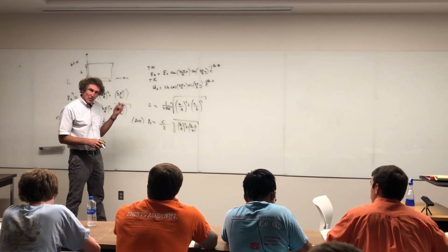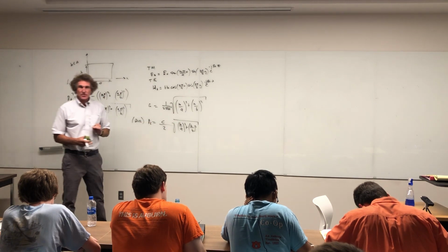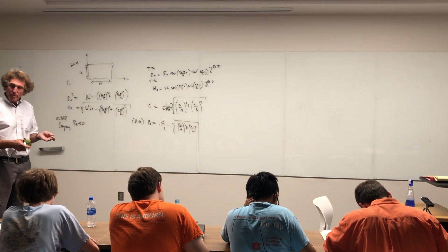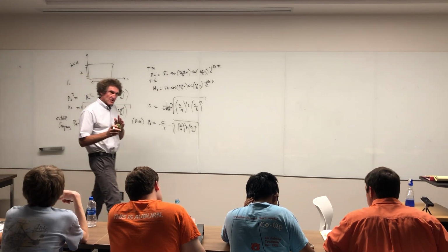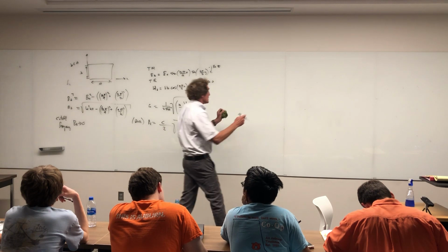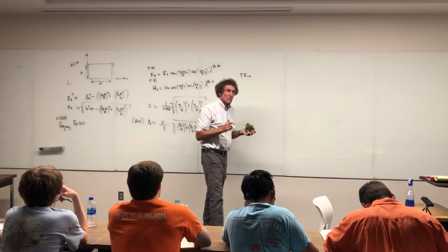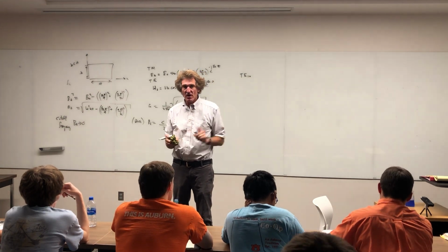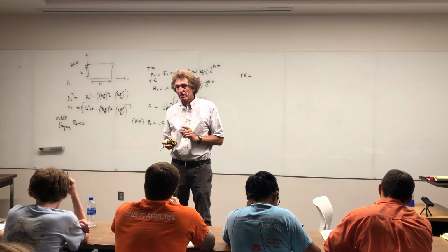All right, now we talk about where you begin with the integers. m and n are integers, right? And a is greater than b. The lowest order mode that will propagate will be the TE10. I'm going to tell you that, and I'll prove that, but you're going to get TE10 as the lowest order mode. That is when m is 1. That's the variation across x, and there is no variation in the y direction.